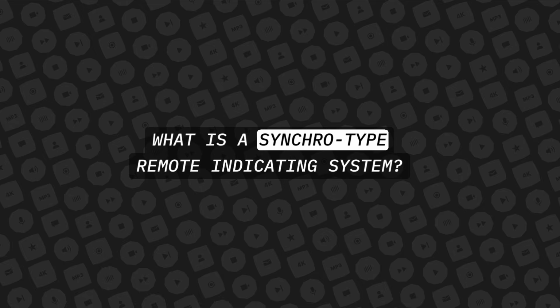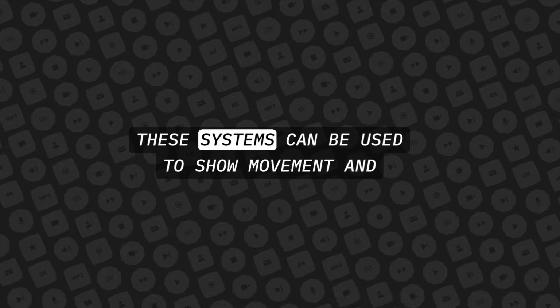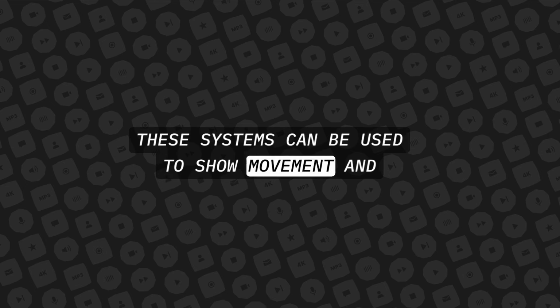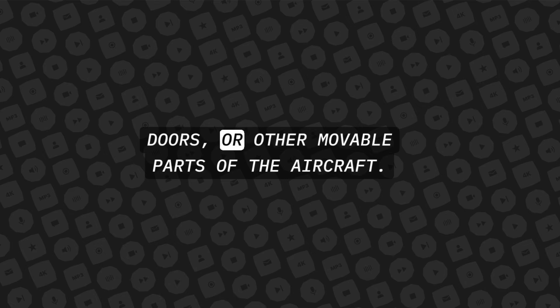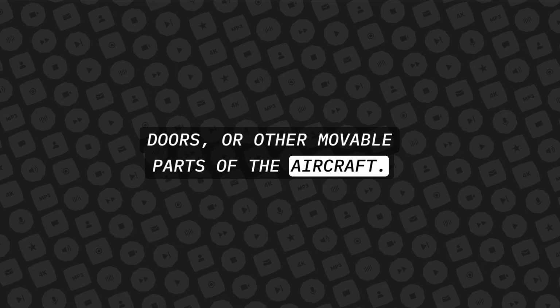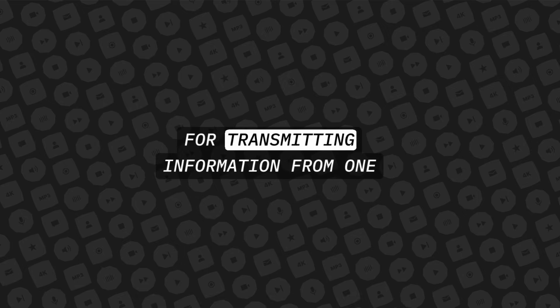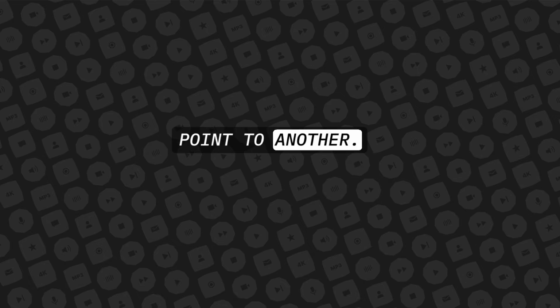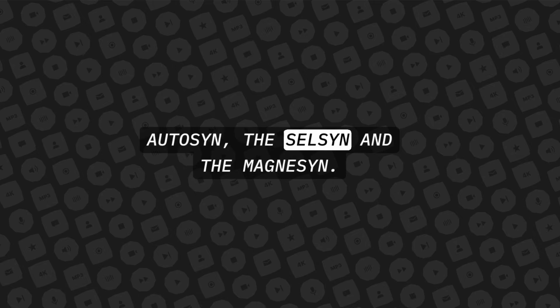What is a synchro type remote indicating system? These systems can be used to show movement and position of landing gear, wing flaps, oil cooler doors, or other movable parts of the aircraft. A synchro system is an electrical system used for transmitting information from one point to another. The three most common synchro systems are the autosyn, the selsyn, and the magnesyn.